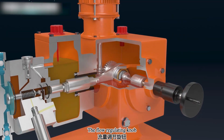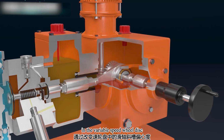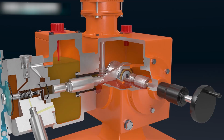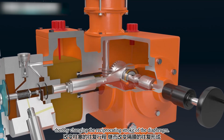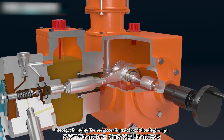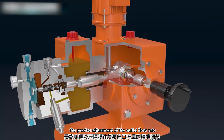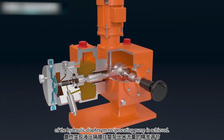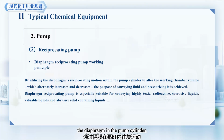The flow regulating knob changes the eccentricity of the sliding shaft chute in the variable speed wheel disc to adjust the reciprocating stroke of the plunger, thereby changing the reciprocating stroke of the diaphragm. Finally, the precise adjustment of the outlet flow rate of the hydraulic diaphragm reciprocating pump is achieved through the reciprocating motion of the diaphragm in the pump cylinder. The working volume is changed to transport liquid.